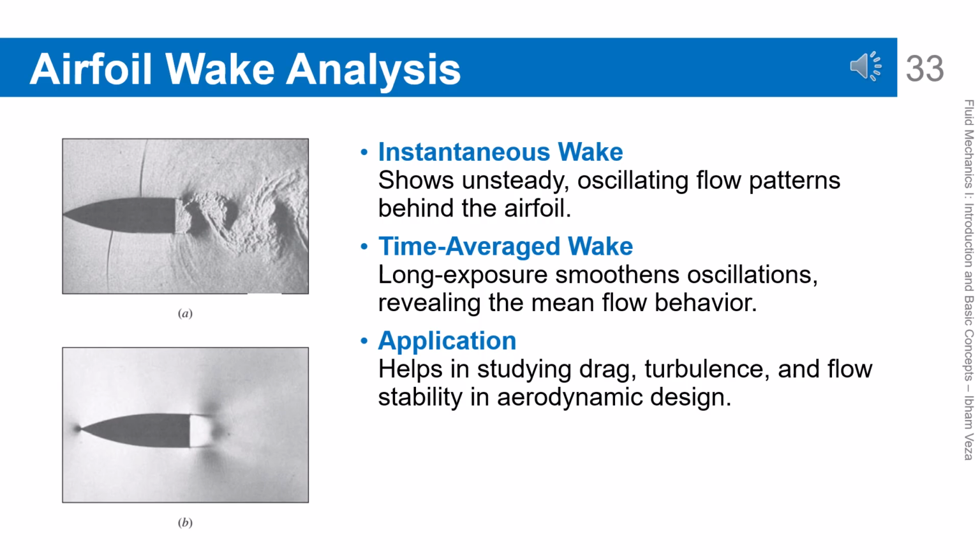Airfoil wake analysis. The instantaneous wake shows unsteady and oscillating flow patterns behind the airfoil. The time-averaged wake shows a smoother pattern representing the mean flow behavior. This difference is important in analyzing drag and flow stability. This visualization helps explain the sources of vibration and noise. This concept is very important in aerodynamic design.